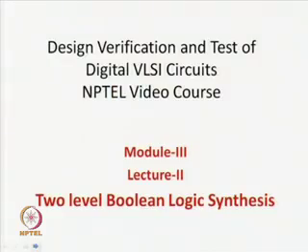As we discussed in the last class, this is a 3 lecture module on 2-level Boolean synthesis. We started in the last lecture with what Boolean synthesis is. In Boolean synthesis we consider the output of the high level synthesis tool, or in other words we take some Boolean functions and try to represent them using the minimum number of logic gates. In other words, you want a simplified representation of Boolean functions.